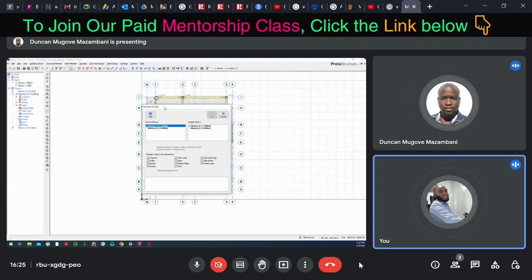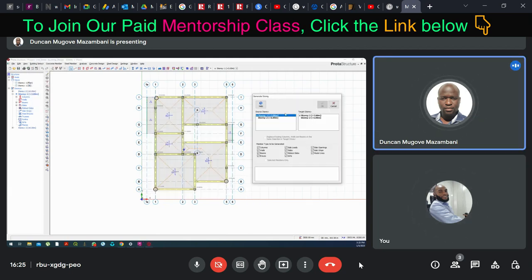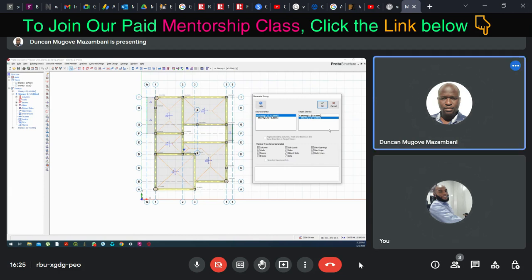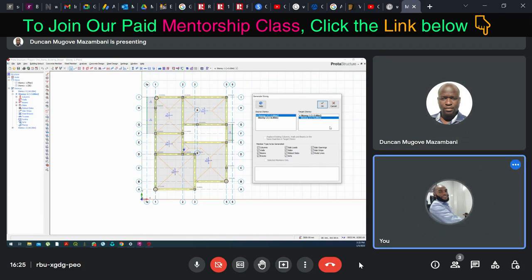Okay, now you can see that we have a source story and also a target story. So our source story is story one, our target story is story two. Now click on the target story, click on story two. Now remove all the slab, check out all the slab, because right now we don't have slab at our roof level. We will be using a roofing sheet for the roof, so we don't have to use slab. Okay, so right now click on OK.